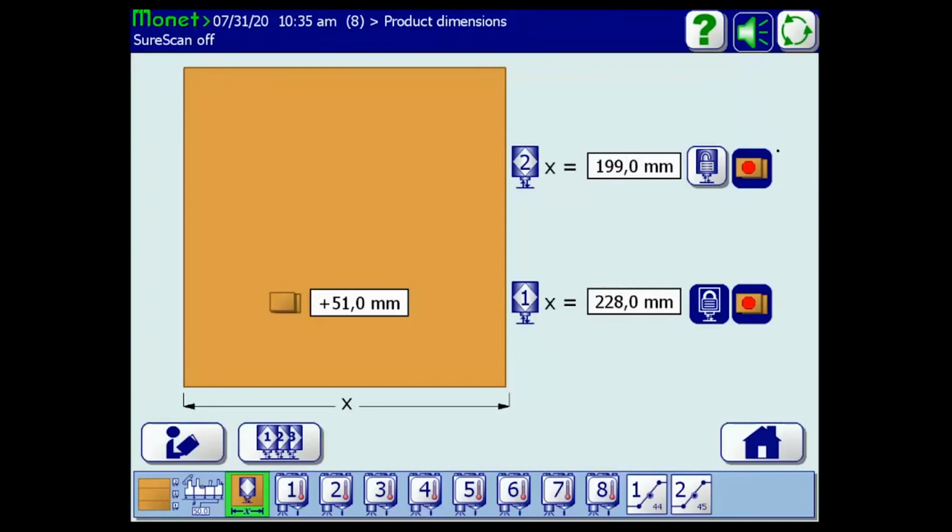So the overlap detection allows the trigger to detect a potential jam up. We consider overlapped cartons as potential causes of jam ups on the machine. So it's utilizing your trigger sensors as jam detectors. And what we have to tell the system is what is our tolerance for excessive length.